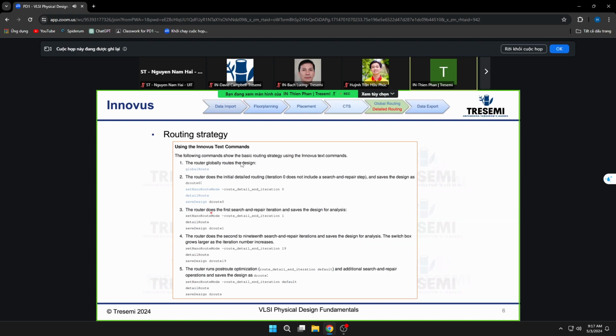And then it's going to try to do that over and over, right? Because more likely you're not going to be able to do it in a few iterations, as the design is so challenging. If it was easy, probably it was able to route it the first time around. There are so many possibilities, so you have to give the tool enough chance to try different things. That's why the iteration comes in.